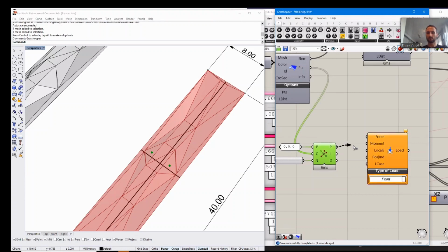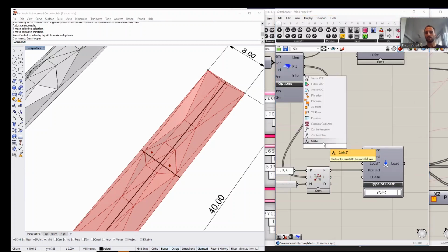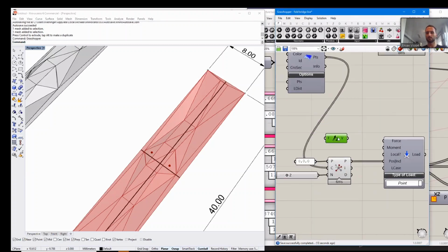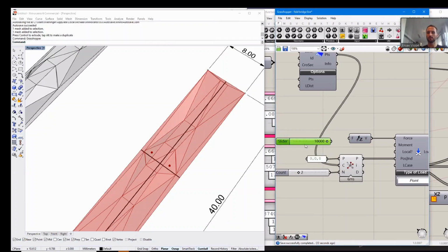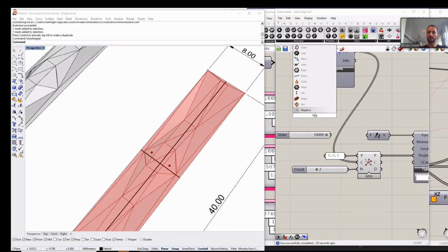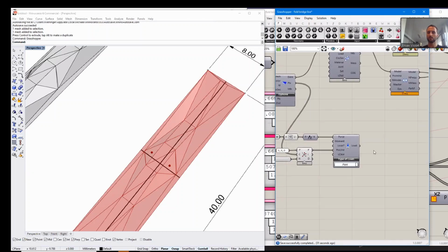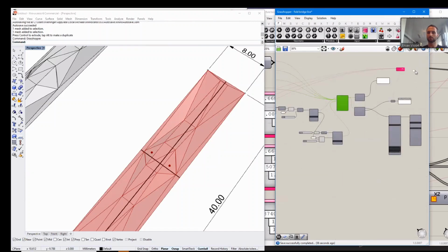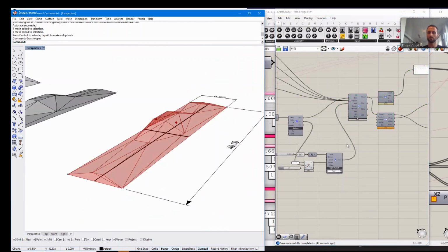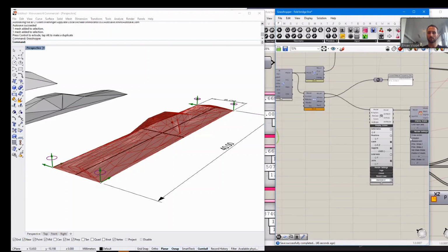The bound points, I'm going to plug into the positions input. And I have to define a force for the loading. So a z vector with a certain value, negative z vector. So we're pressing downwards onto the middle of the bridge, and plug the load into the assemble models load input. And if we show the model view component, it would actually show us the loads.